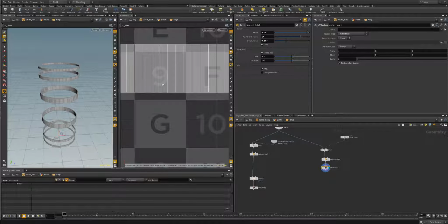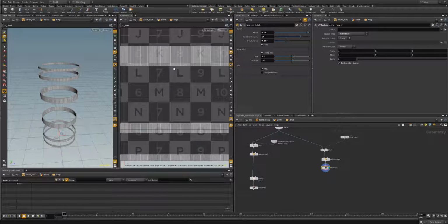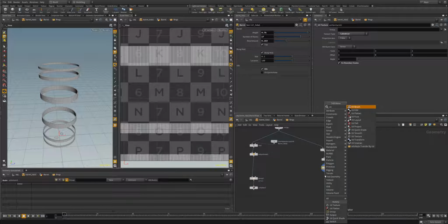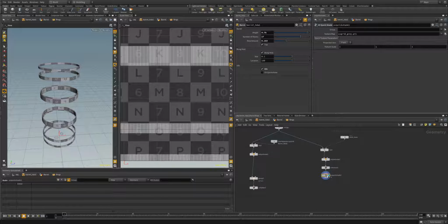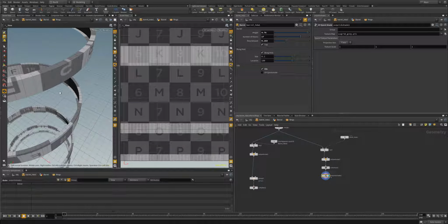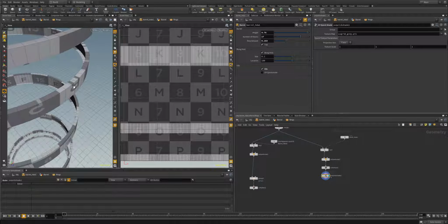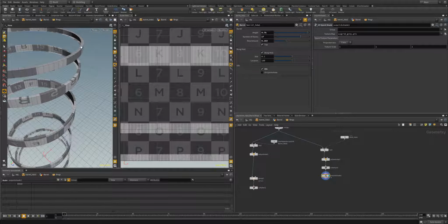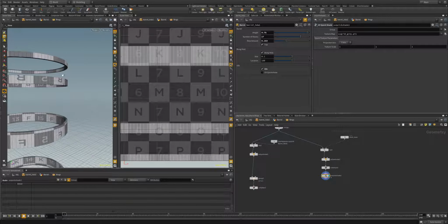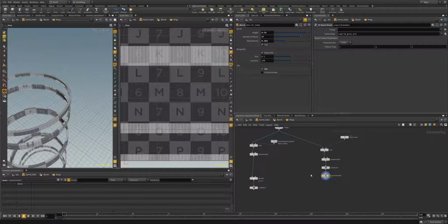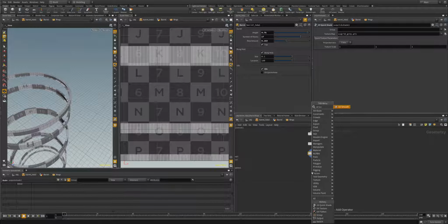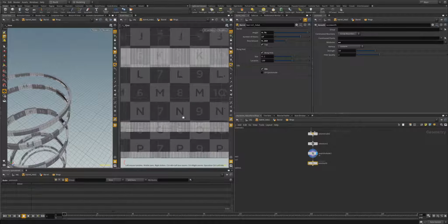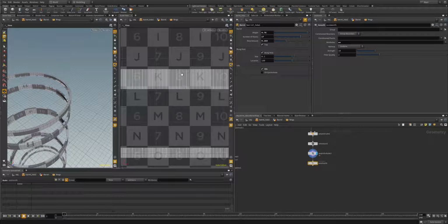And it's not showing it, but if I put a UV quick shade on and we take a look at the sides of our barrel, see if one lines up. So see how the letters stretch across here? We're actually not UVing the top and bottom edges of our cylinders here. But there's no border edge here, so we should be able to use the UV smooth to kind of relax or flatten out the UVs for our barrel rings. So we'll go ahead and hit the smooth, and we'll see that that's already working a lot for us.